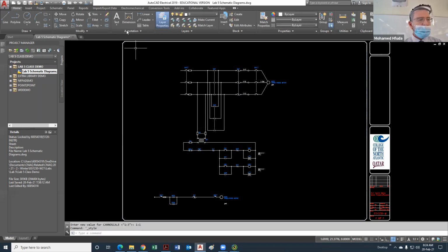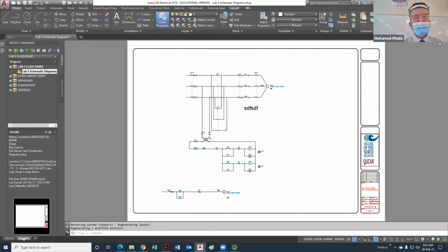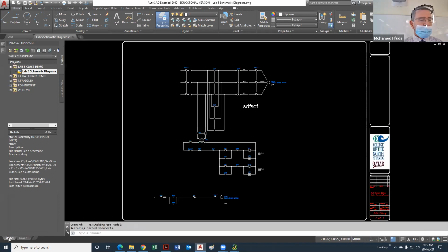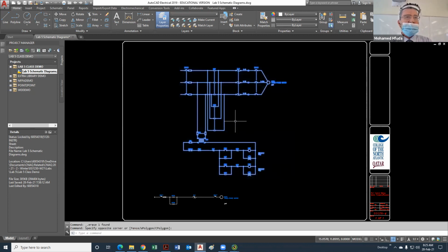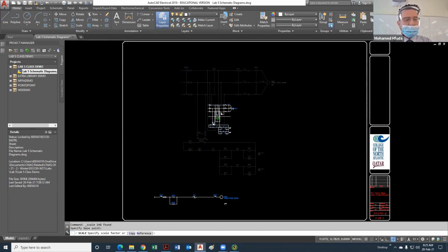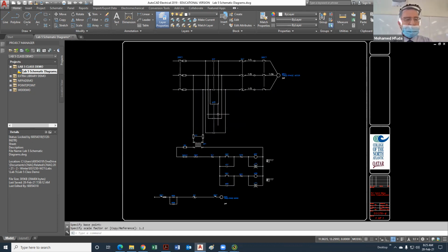And I still want it to be Arial. Yeah, that's more reasonable. Yeah. If you want to set it annotative, yes, you can, because you're actually controlling the size. And I suggest, don't do this until later on, because you're going to need to scale it. So how to scale it? Scale, click somewhere, and let's say 1.2, for example, scale there, or 1.3. You can try.